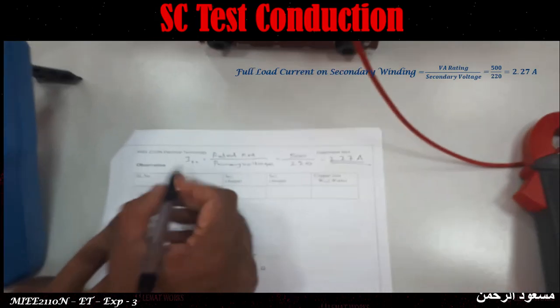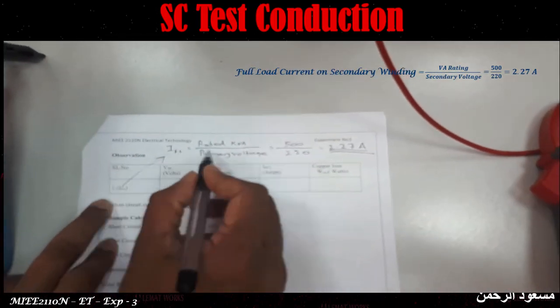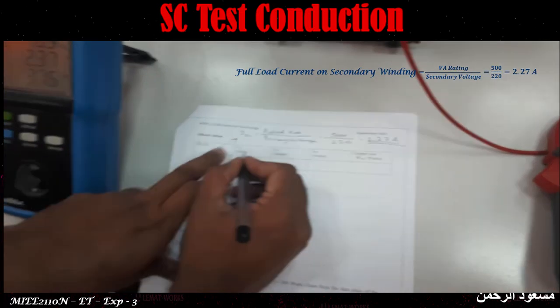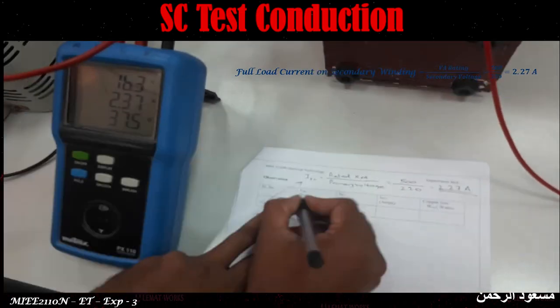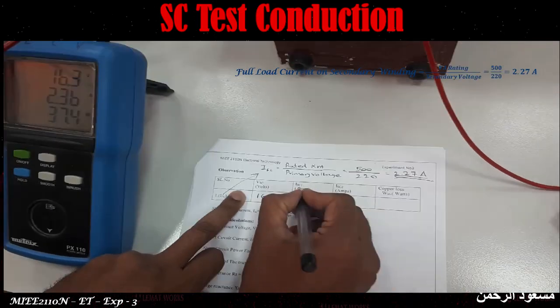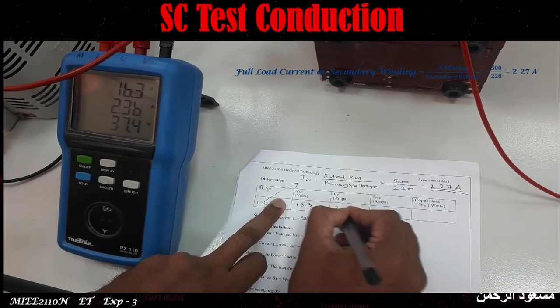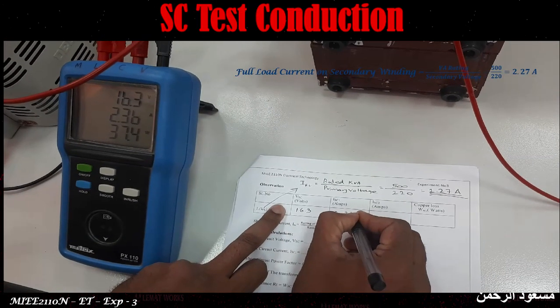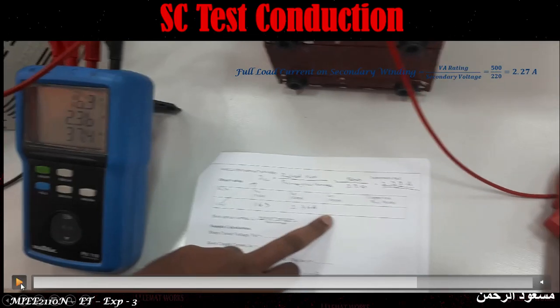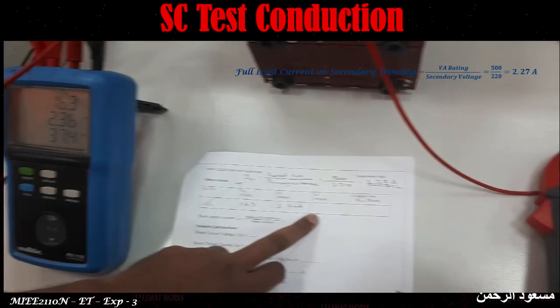IFL is calculated in the log report also: the rated VA divided by the secondary voltage or primary voltage. If you divide by the primary voltage, you get the primary current; if you divide by the secondary voltage, you get the secondary current. Of course, our transformer has the same voltage rating on the primary and secondary side, so you will get the same value.